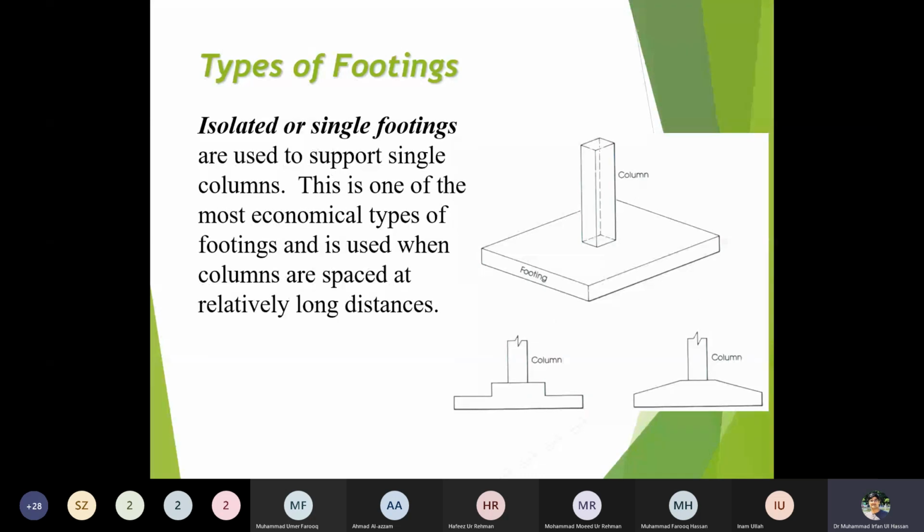When your building column spacing is larger and the load acting on the columns is lesser, you can select the isolated footing. Isolated footing is a good option, but normally for lesser load, for a lesser number of stories, when the soil is also good and there is lesser chance of differential settlement. Due to the larger load, the column has a larger punching shear area, so you can see in the bottom zone the thickness of the pad is larger in the column vicinity to avoid punching shear, and it is lesser at the end because there is zero shear at the end.